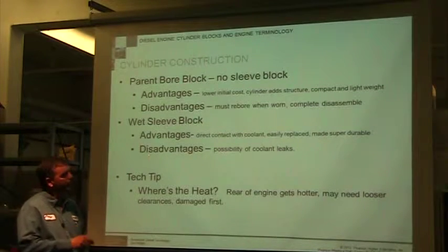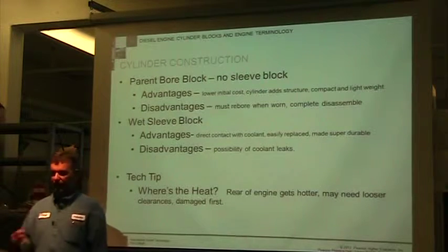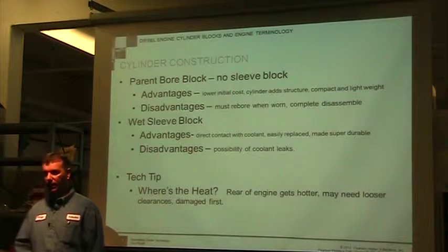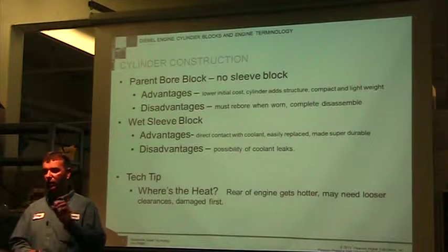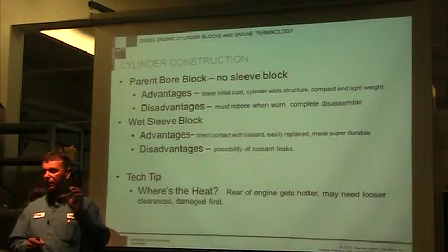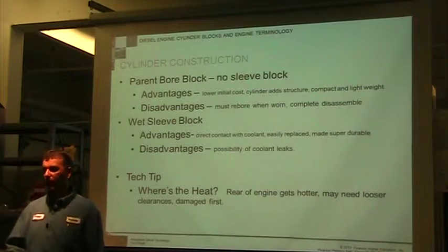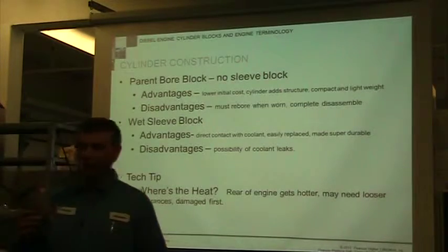The disadvantage is coolant leaks. The bottom of that liner has to have some sort of seal, and usually it's some kind of O-ring. If you run water in it, you'll see where that O-ring goes. That O-ring will have pitting around it, and if the block gets pitted where that O-ring is, it's going to leak. And when it leaks, where does the coolant go? Goes into the oil.